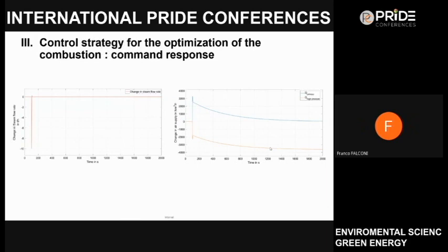When your primary air goes up, you are basically burning more waste because you are adding more air to the system, so that the system can use more oxygen to burn more waste. And at the same time, the high pressure air, which is the air used to maintain the combustion chamber within a certain temperature, also drops. So what we are doing is burning more waste and cooling the combustion chamber less, in order to have a bigger temperature to compensate this disturbance on the steam flow rate.